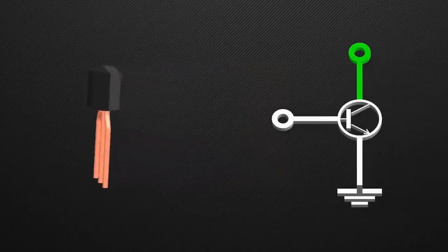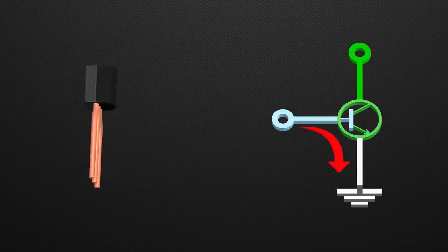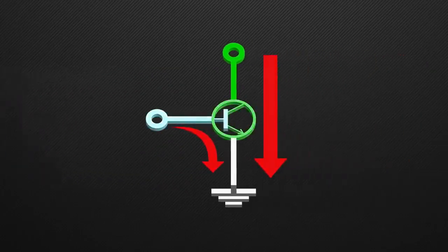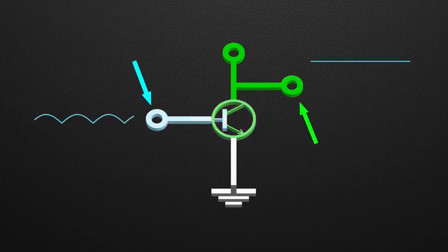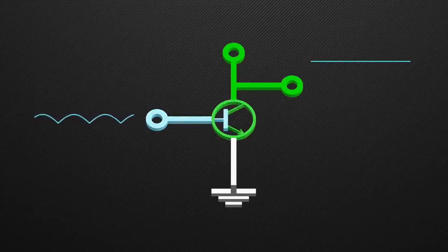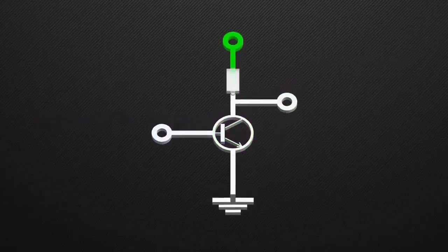You would know that the transistor can amplify the base current, by its gain, to the collector current. Hence, we will use the transistor to amplify the voltage applied at the base to a higher voltage at the collector. In this circuit, the output will always be VCC, as it is directly connected to the source. Thus we add a resistor between them.